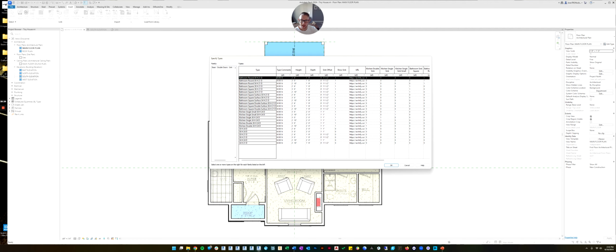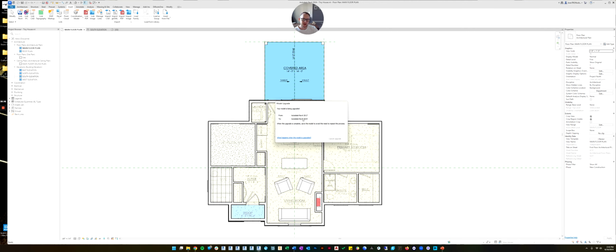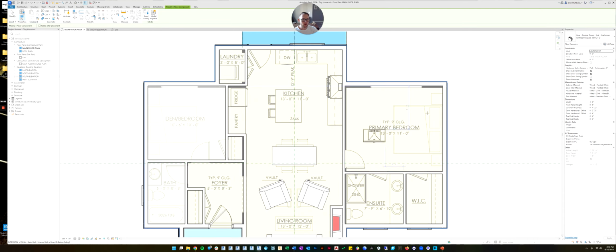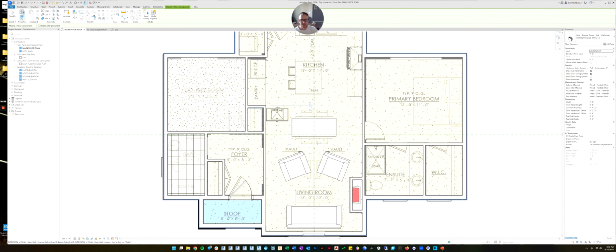So we're looking for a bathroom with, let's do a square sink. And a bathroom is usually 30 inches tall, but if you want it to be comfort height, you'll do it 36 inches high. So we're going to pick 36 inches high, 21 inches deep, and we'll just bring in that one cabinet. So it's going to convert these because they were made in an older version of Revit. So it'll convert it and then it will put it in your model. So now we can go to the architectural tab and we can go to place component, and it should already bring in the sink for you.